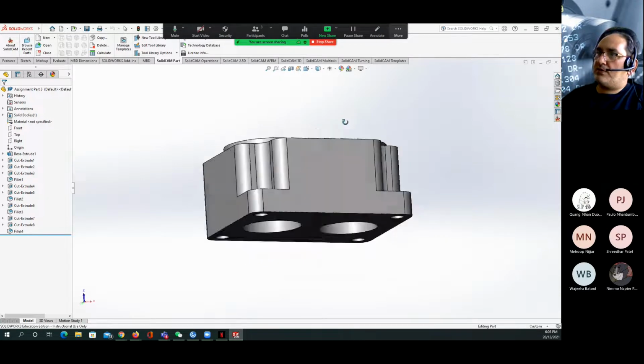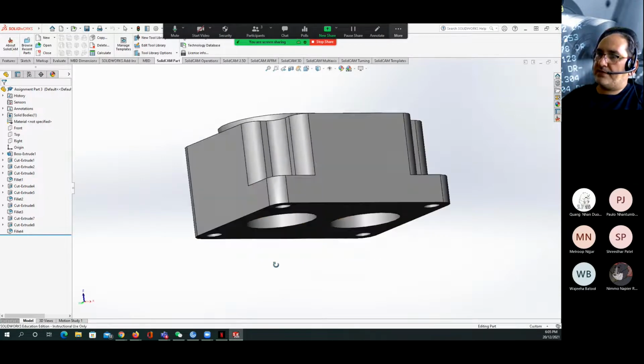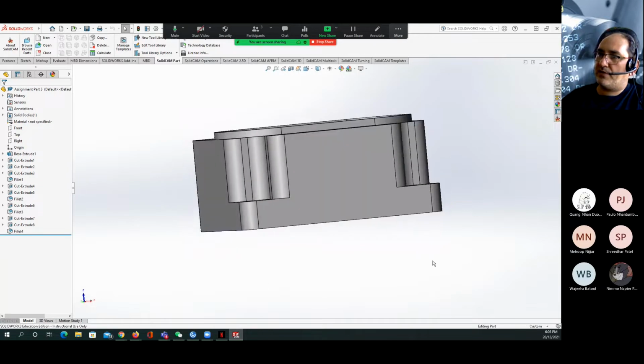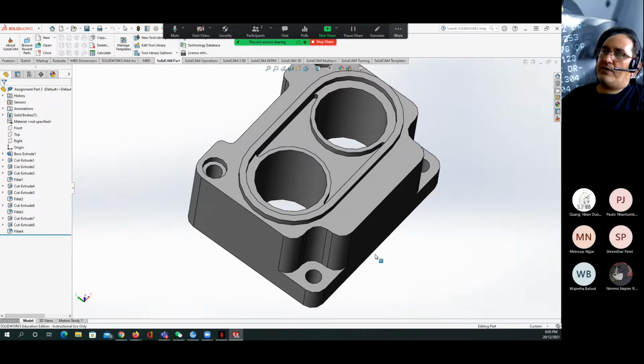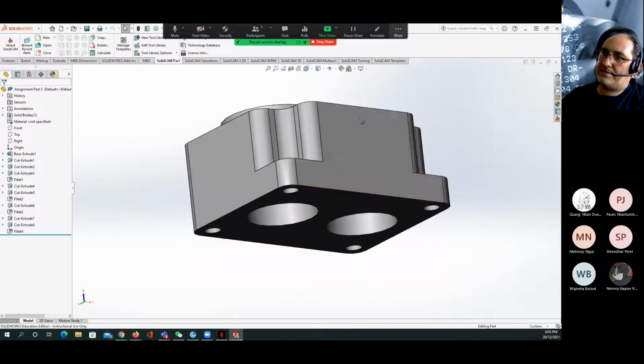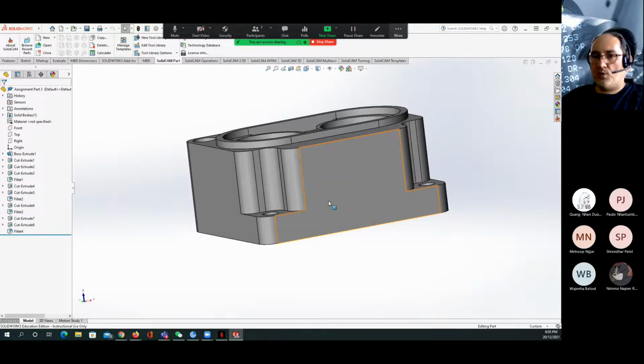We're going to have nozzles on the second level, because this is the top level. We are going to have a lower level here with all the tubes for the fuel to pass through. Whenever we increase the airflow going from here, the outside air going to that side, we're going to have some negative pressure. It's going to pull more fuel and send it to the induction first, and then we send it to the car cylinders, and thus we make the engine work.